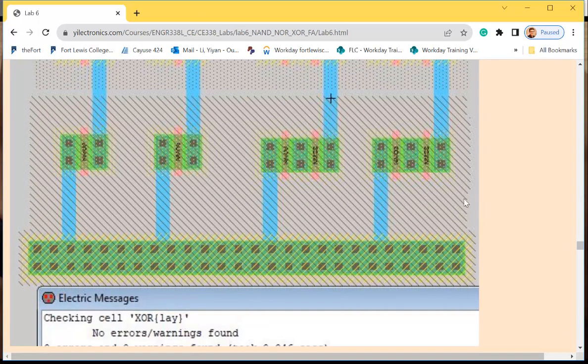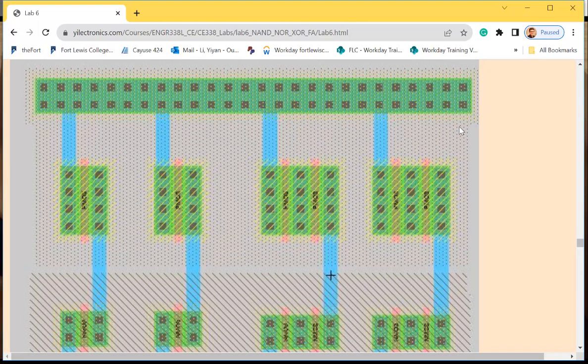Why do I have to draw that thing? The same to this N-well. See, I couldn't see that clearly, but I did that. So you grab a PMOS, it comes with that N-well because by default it puts the PMOS in the N-well. However, if I don't draw another N-well rectangular shape here, there will be a gap in between the PMOS N-well and the N-tap's N-well.